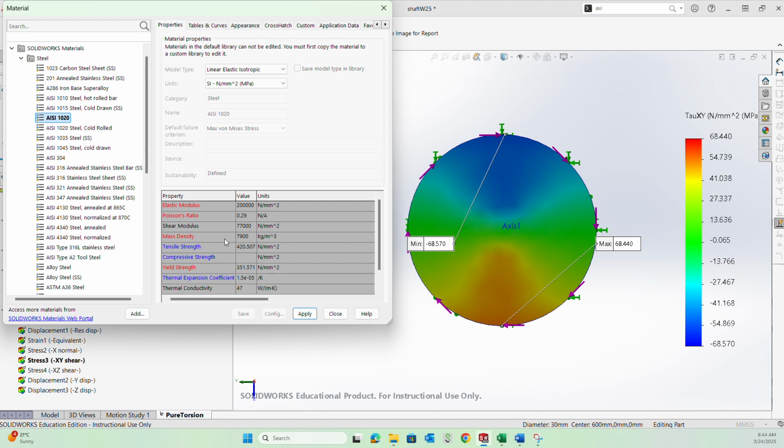In particular, for ductile metals, you can use the estimate of the shear strength being half of the tensile yield strength, but that will only be applicable if the material that has been given to you is a very ductile metal. Otherwise, use the estimates that I have discussed in the slide.